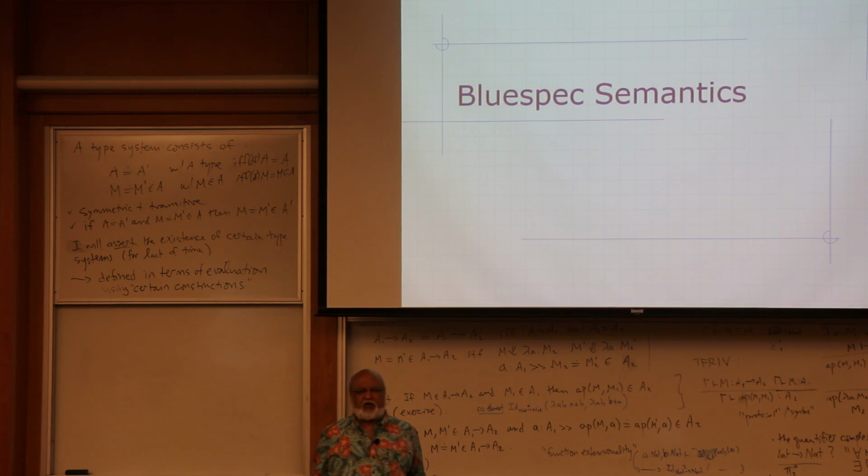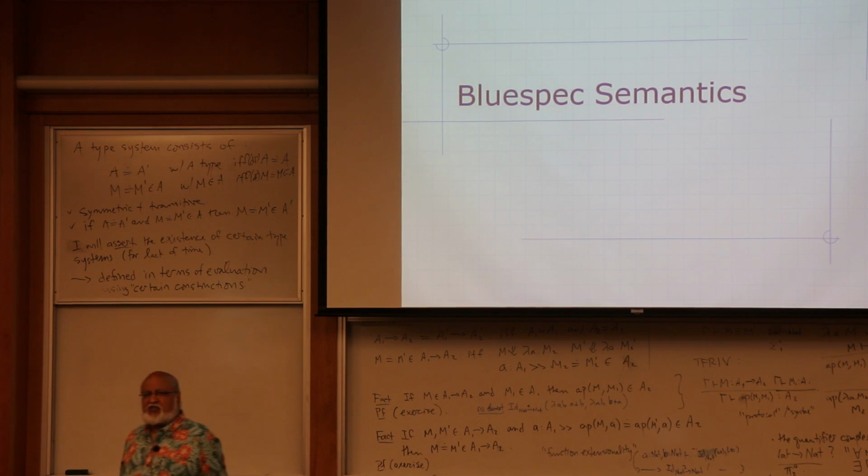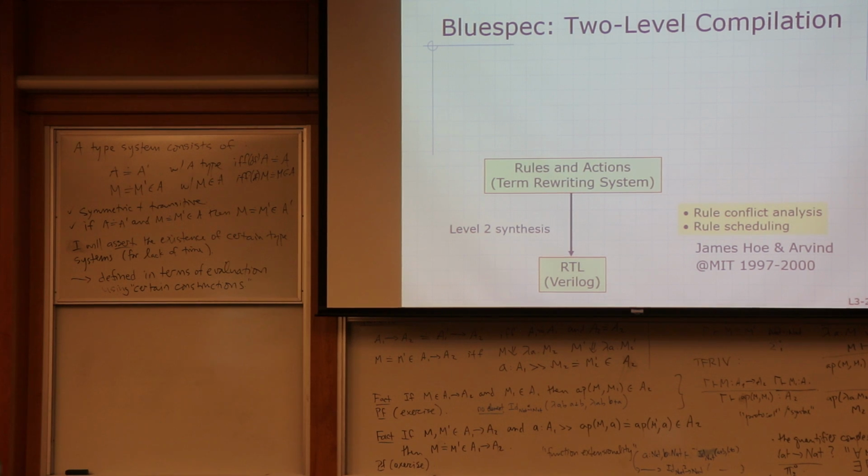Okay, so now let me talk about the semantics of Bluespec. Just to get the big picture of what we have discussed previously: we have a program, and the compiler has taken this program and generated... no, not machine instructions. It's directly generating this hardware. It's generating a description of this circuit, and circuits at this level are known as RTL, Register Transfer Language. I want to connect this hardware with the programs which I'm writing.